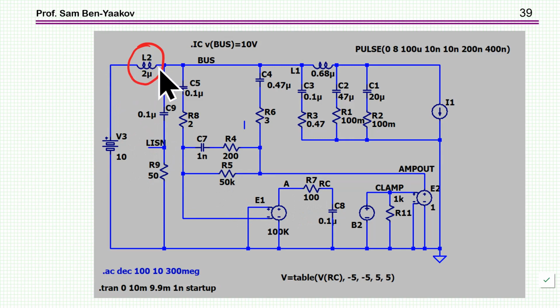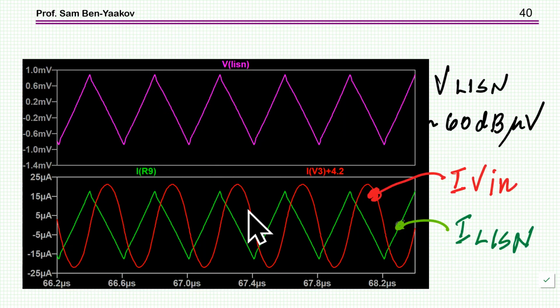Ideally, you like the current here to be very low, and this is why I like to put a high impedance here, but unfortunately I cannot do that. If I look now at the currents, they are of the same order of magnitude, which means that this is really not an optimal design at all, and that this is an underestimate, because there is another current which is not measured by the 50 ohm, but it's 1-to-1, so the increase here is like 3 dB, so it's not that much.